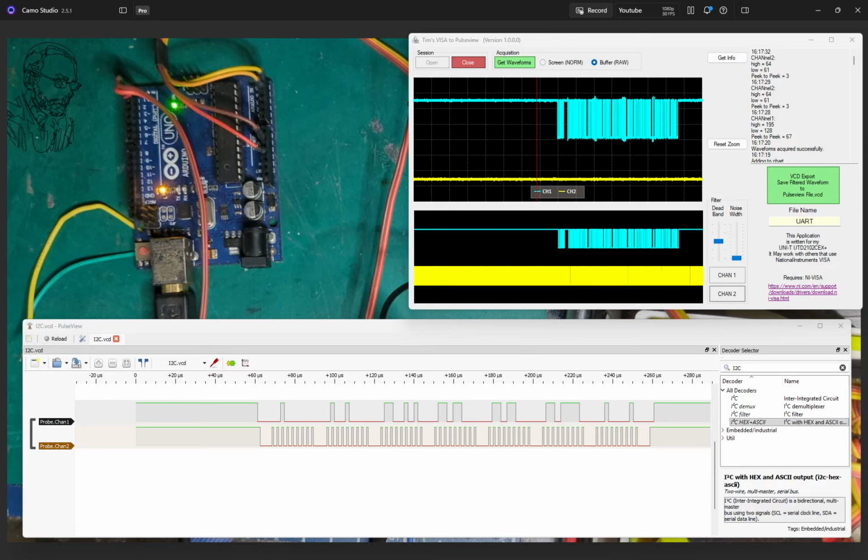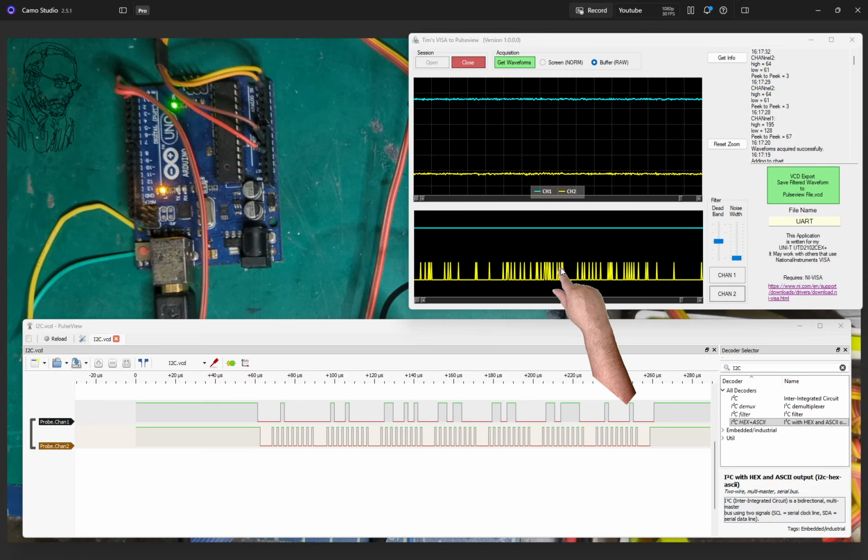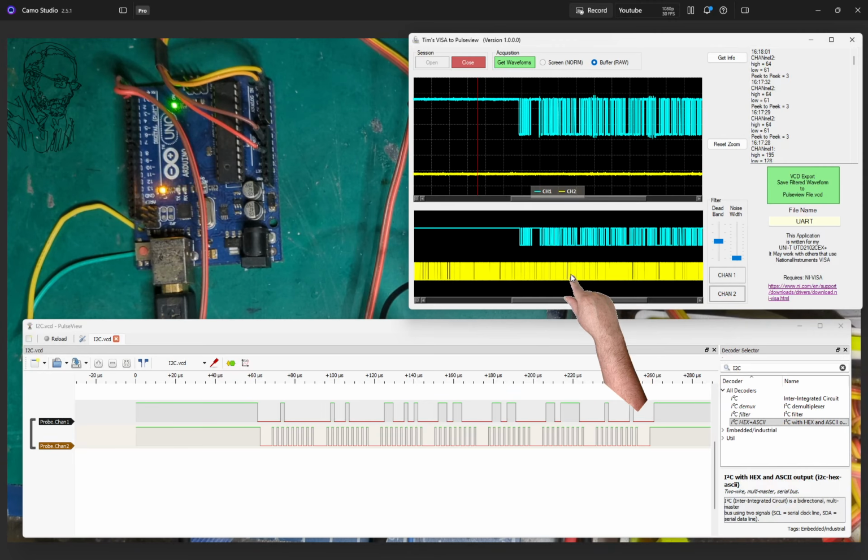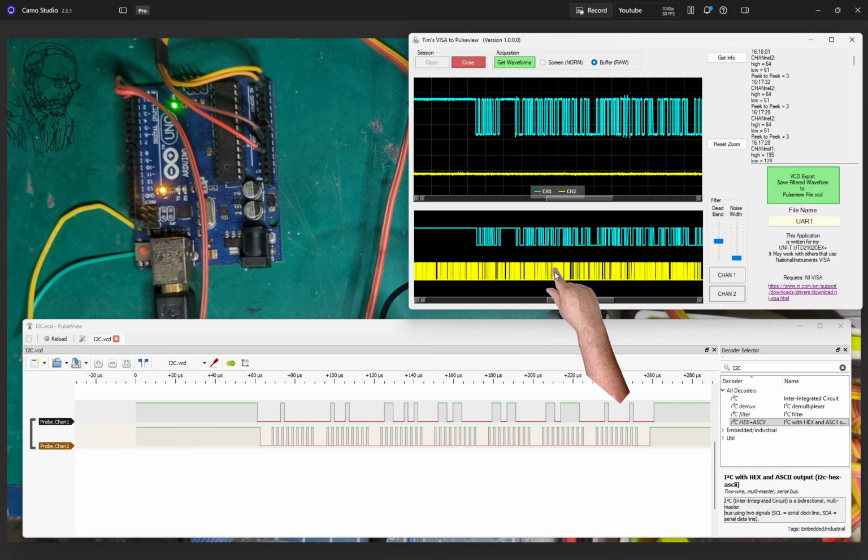Right, what I tried to show you before, I've swapped the channels around now, but basically I've turned the noise down to 0, and when we filter it, it's going to filter all the noise out, which is all these little ripples, as actual pulses. But when I filter channel 2, this is what we get. We pick up all the noise, and we actually filter and convert the noise to ons and offs.